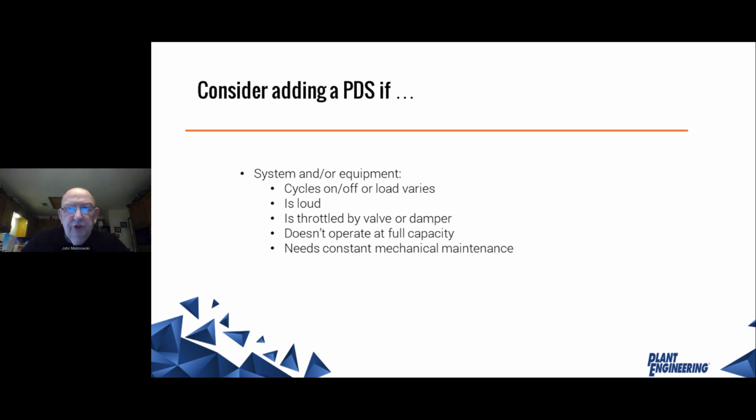So why should you add a PDS? If your equipment cycles on and off, or the load varies, or it's too loud, or you're throttling it with a valve or a damper, a pump or an HVAC system, or it doesn't operate at full capacity.